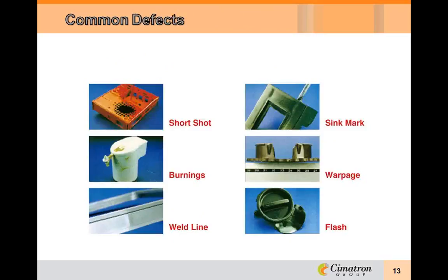In addition to the challenges that I just mentioned, under the best of conditions even, injection molding is still a complex technology that also introduces these challenges. If not handled properly, there may exist various flaws either by defects in the mold or improper mold process settings. And here we see examples of a short shot. Of course, a short shot is a molded part that's not completely filled.